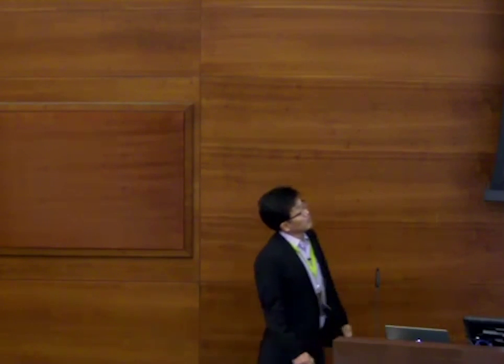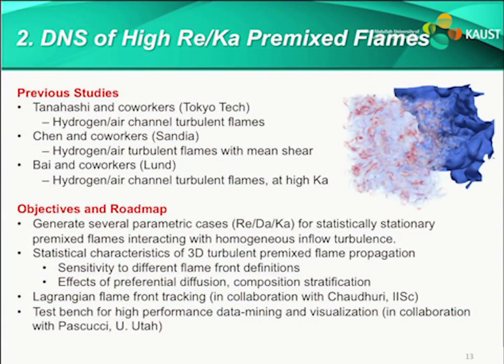So moving on to the premixed flames, there have already been a number of presenters before me talking about it. Even this standard channel premixed flame has been done by many people before, including Professor Bai here, who just presented today. We are just trying to do a nice, clean channel turbulent premixed flame. And we are trying to also push a little bit the boundaries of the Karlovitz number that many people already talked about.